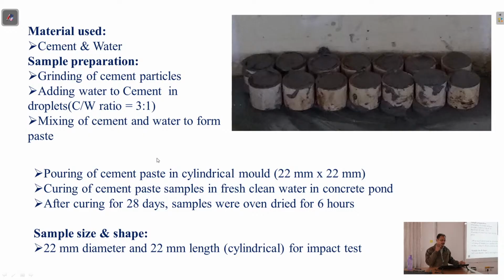So gradual mixing, and of course you might have seen the process of making such a thing all the time. Gradually after mixing cement with water, that is placed in the mold for 24 hours, and thereafter these were soaked in water. Ideally it is best to cure it for at least 28 days, right?